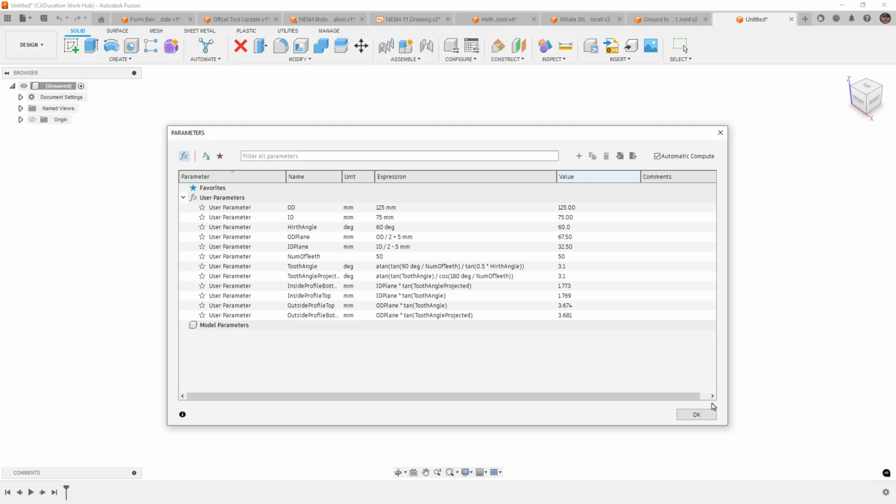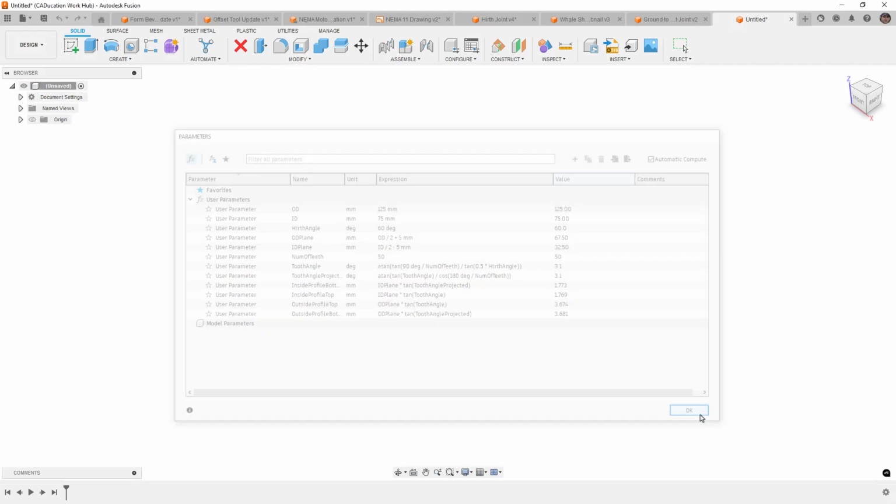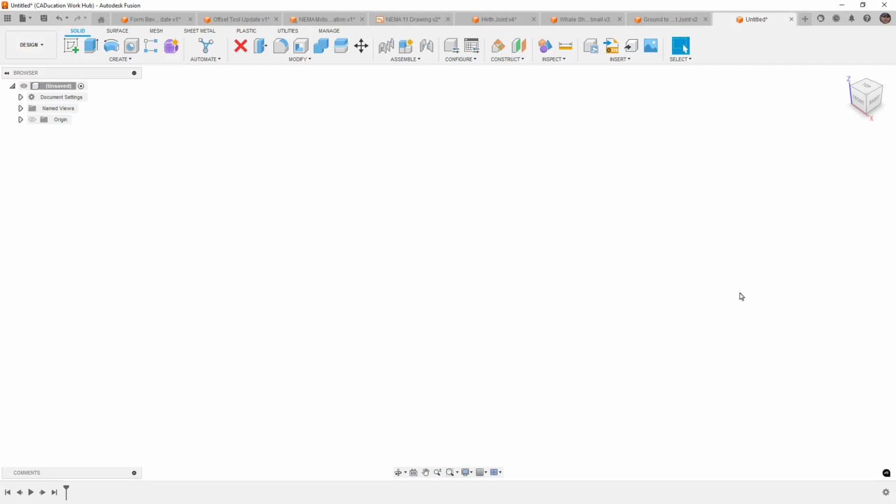So what this allows us to do is to generate parameters that are common for things like our injection molded designs, if we want standard draft and wall thickness. And we can just export those as a parameter that we can import that CSV file, basically. So it gives us the ability to build out these sort of complex templates, even though we don't have a traditional template file, and we can bring that data in. So that's a really nice improvement.